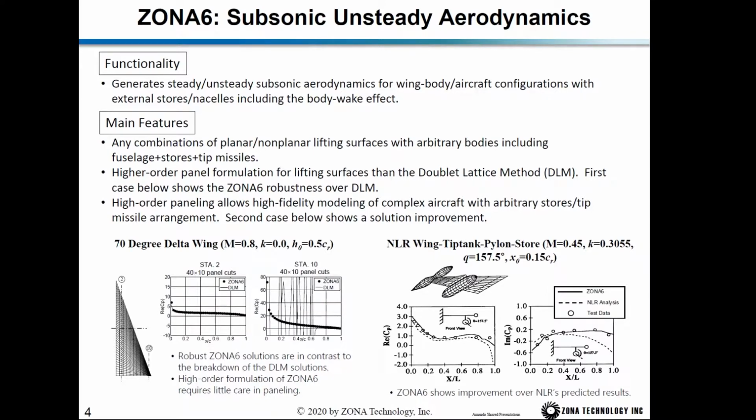If you look at the NASTRAN Aeroelastic manual, it says if you use the double lattice method, you have to restrict the panel aspect ratio to be less than 3. Okay, so if you look at the aspect ratio of the boxes along the wing tip, its aspect ratio is very high. Therefore, it violates this modeling restriction, and therefore gives you this bad solution from the DLM.